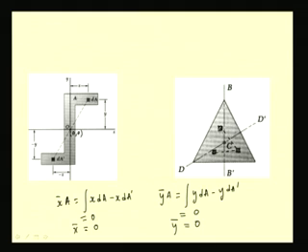So, if the mass center or the centroid has to lie along this line as well as along this line, we see that the possibility exists only at the point of intersection, that is C. So, this discussion holds good for any shape, and if we have the lines of symmetries, then we can advantageously use it, and we can only find the other coordinate that has to be found by, let us say, the integral.